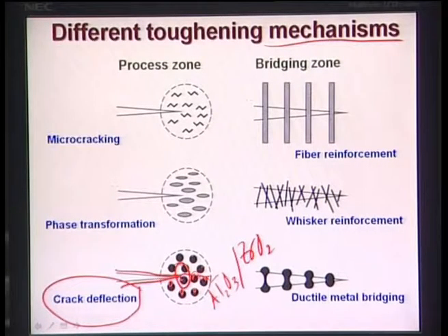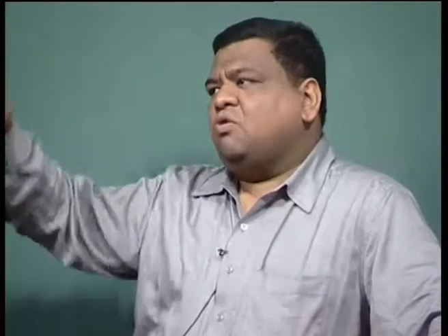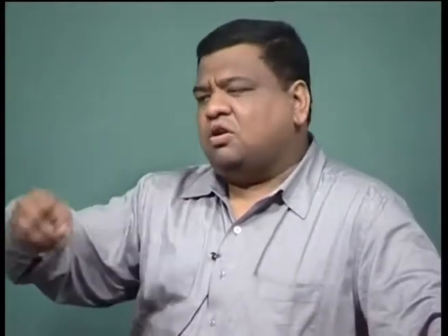However, since a number of particles are present on its crack path, the crack path will be deflected by the particle boundaries. Crack path tortuosity means a deviation from straight line propagation. A highly tortuous crack path goes sinusoidally, or like this. So if the crack path tortuosity increases, the total driving force available for crack propagation is reduced, and then the fracture toughness will increase.